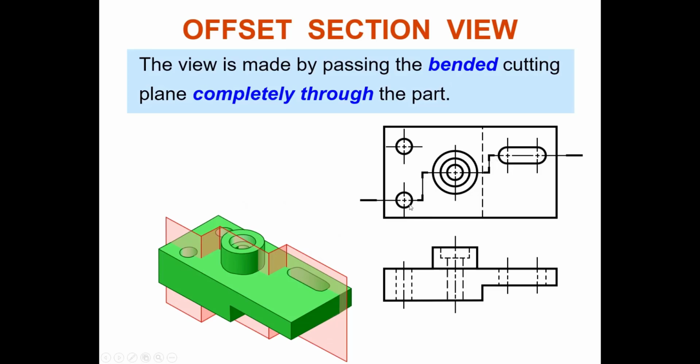We have corners, zigzag, like an L shape. Take note, at the end it is bolded, thicker, L corner, thicker, L corner, thicker, and then extends a bit thicker. Be careful about it and take note of your offset section. So it describes the internal holes, the round hole, the C-bore, and the slot can be shown.